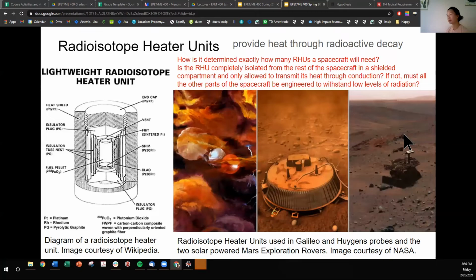We can do that by collating the operating temperatures of the different components on board the spacecraft. Then, once you have your components configured in some geometry, you can run a thermal analysis and probe the cold spots, to see if all the components will survive.